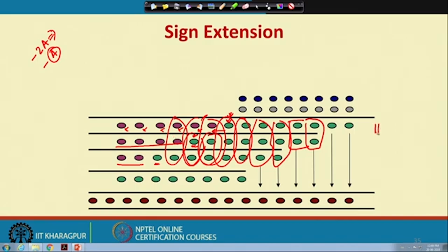So, if I use generic carry save, that means the Wallace tree multiplier, at that time the depth I need is more than, here I need 4, but if I use only Wallace tree, at that time I need 8 stages. Okay. So, this is the sign extension method which I need to follow whenever we are using this multiplier architecture. Okay.